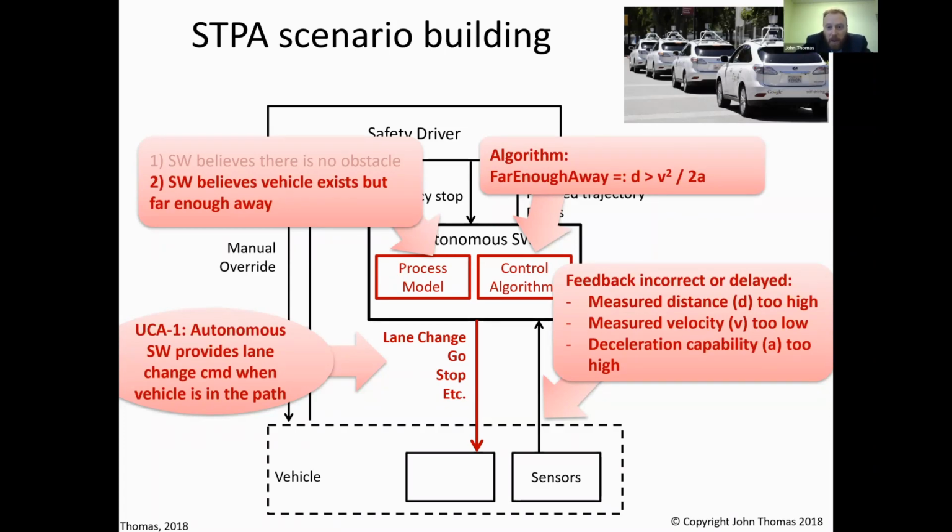An average was the mean. It was the best optimization of all the goals that we have. We don't want it sitting there either. Yeah, so we assume it's an average vehicle with an average deceleration capability on the road derived from real data. And that's what we use in this algorithm to determine if there's enough time for us to merge over into another lane.